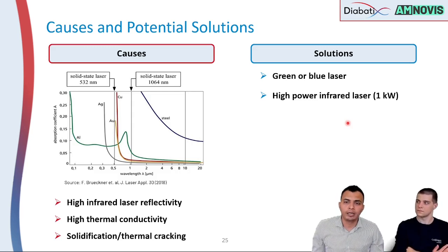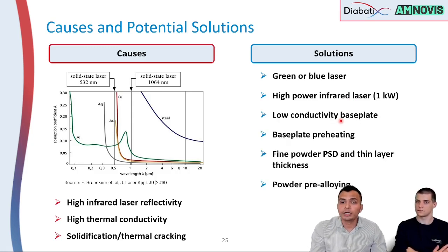That's where your optical absorptivity increases in this approach, and you could manufacture a dense part. However, there are two major challenges. One, because of this reflectivity, it might damage the optical system of the machine and also some hardware components. The second is that the keyhole itself is not stable. So keyhole mode itself is not stable, so it also has its own challenges.